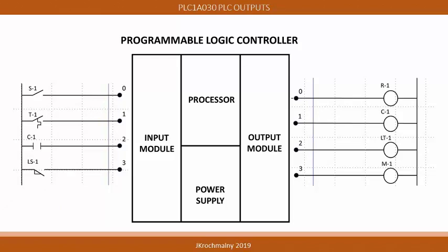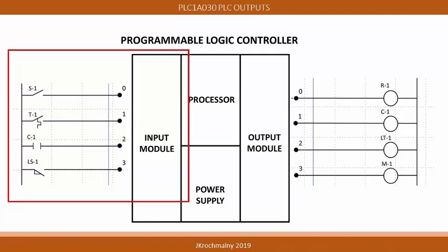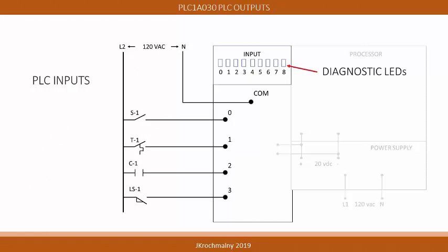Using this type of PLC architecture, PLC controls can make use of lower voltages and currents to make decisions and gate higher voltages and currents to affect changes in the controlled environment. In this graphic, another voltage, not one coming from the Programmable Logic Controller itself, provides the power to the input devices. Input termination screws become electrically active and allows for an LED to illuminate, indicating voltage present on those screw terminals.